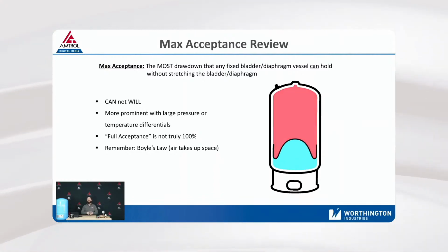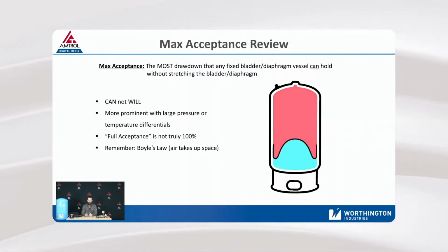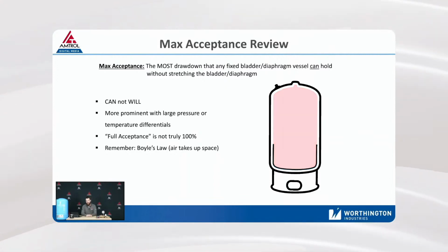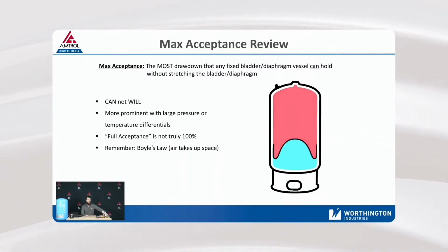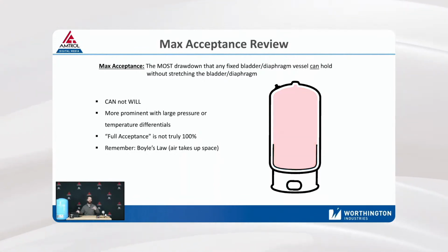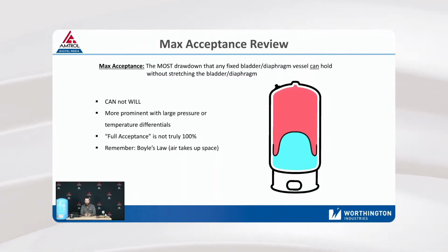So for an L series, again, that's probably the most popular one, they'll calculate their expanded water and say, I have 300 gallons of expanded water, I'll use a 300 gallon tank. No. You're going to have probably a 500 or 600 gallon tank because only 50% will be used for drawdown, depending on your pressures. So it's very important to note.